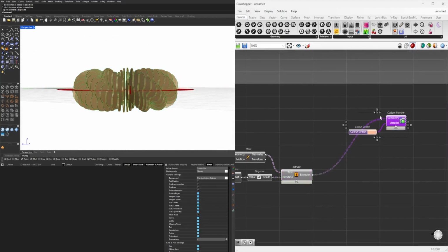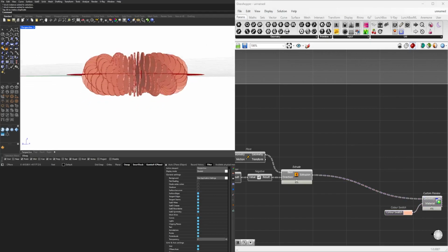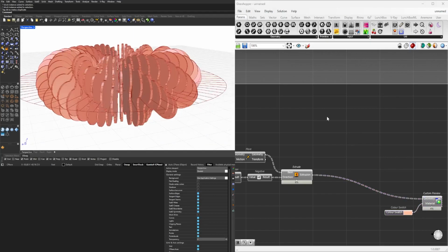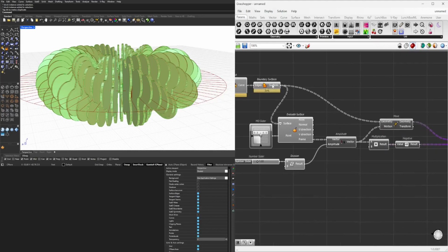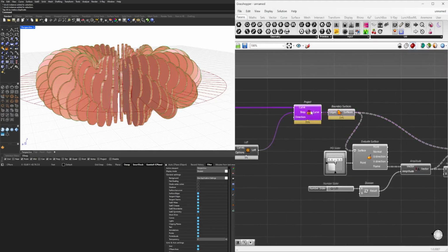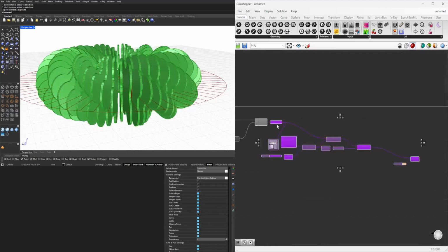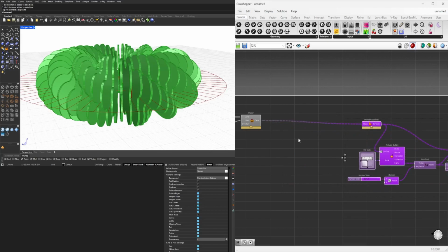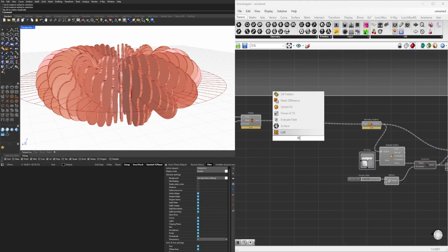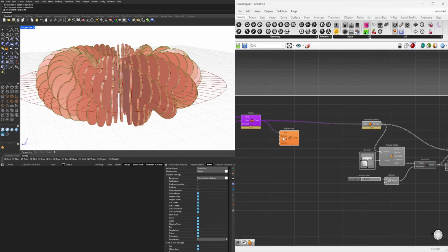All right, let's get on to making this an architectural space inside. So look, we extruded this, which was this surface. And this surface is created from those curves. So what are we going to do? Take those curves, create some space here because we're going to be designing in this area. We're going to offset. Let's try that again. Offset curve. There's a lot of them, so it's going to offset all of those at once.